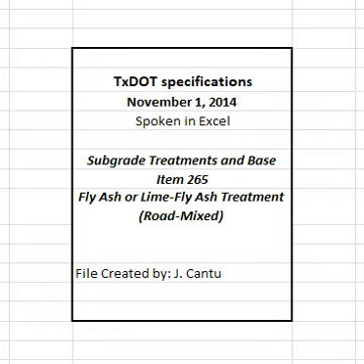5.1.1 Hydrated lime. 5.1.1.1 Dry. Lime will be measured by the ton, dry weight. 5.1.1.2 Slurry. Lime will be measured by the ton, dry weight, of the hydrated lime used to prepare the lime slurry at the job site. 5.1.2 Commercial lime slurry. Lime slurry will be measured by the ton, dry weight, as calculated from the minimum % dry solids content of the slurry, multiplied by the weight of the slurry in tons delivered.